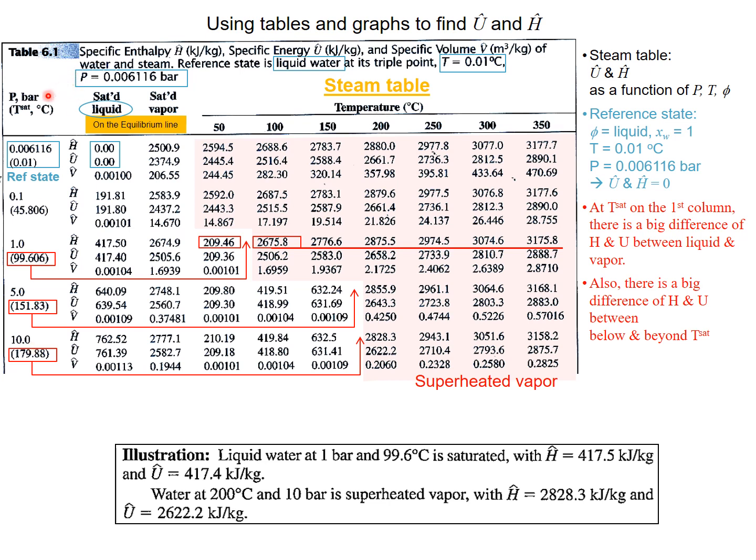And below the pressure values, you can find some parentheses, and inside of which we have some value. That is the saturated temperature in Celsius. As you know, we have a one-component system here because we are thinking about only water, and we have two phases, liquid and steam or vapor. So let me calculate the degrees of freedom by the Gibbs rule.